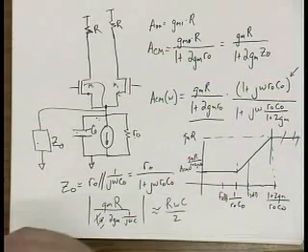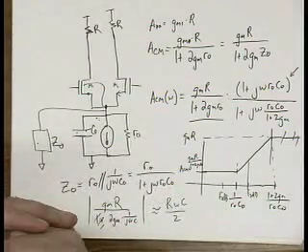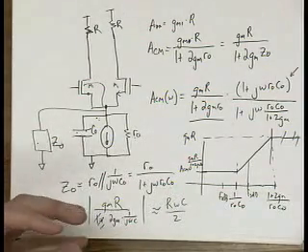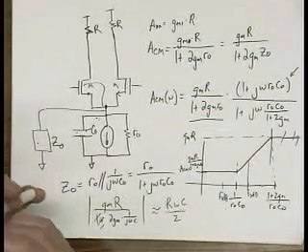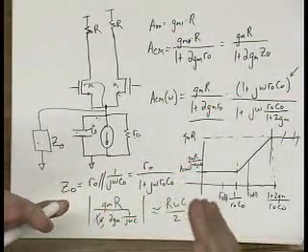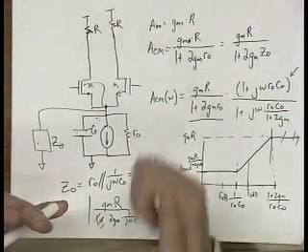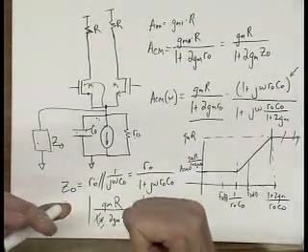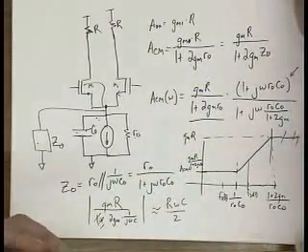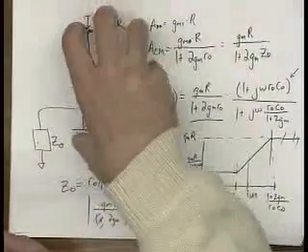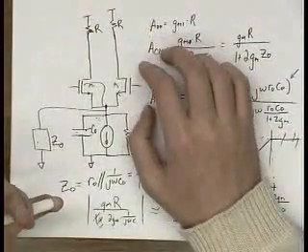So the two areas, as I said before, to focus on are frequency response and good biasing. Good biasing might mean, depending on how you choose to implement your circuit, having bias currents that are totally independent of supply. That's one method. But if you do this totem pole thing, which might not be such a bad idea, you might actually need a portion of bias that's independent of supply and a portion of bias that's directly dependent on supply.